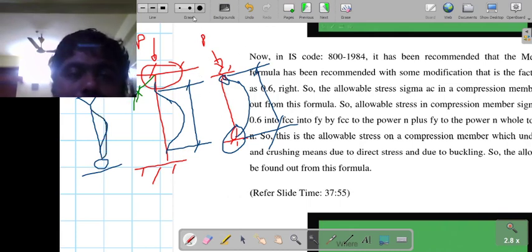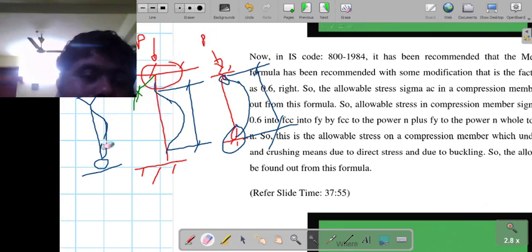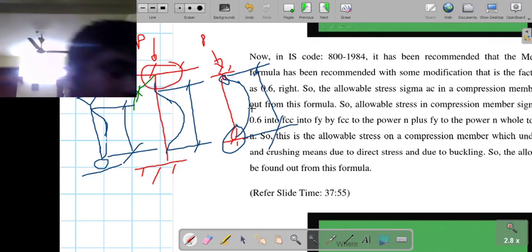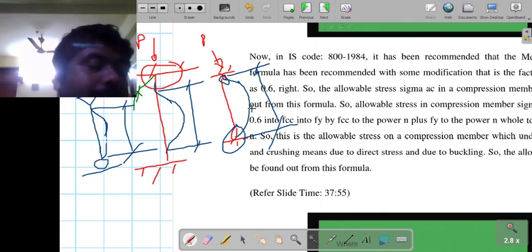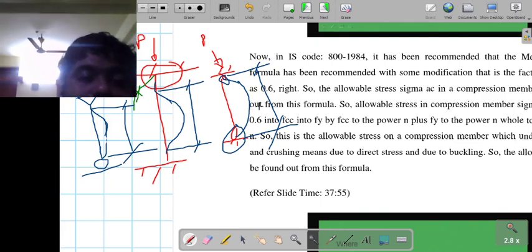So in this case the effective length will be from this location till this location. Based on this guideline, it is done experimentally, and a table is given in the code books, from where we can directly take the value of effective length. For this type of support, the code book gives that the effective length will be 0.65 L. So what is the code book table given? Let us see directly from the note itself.